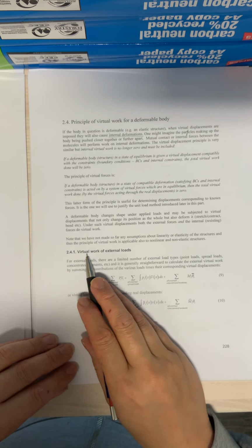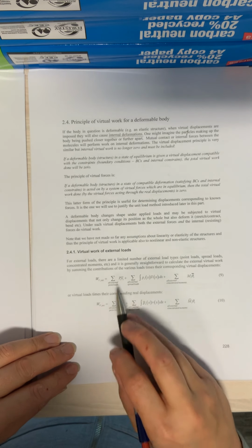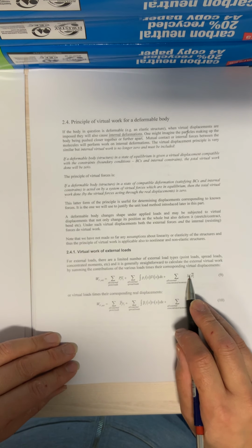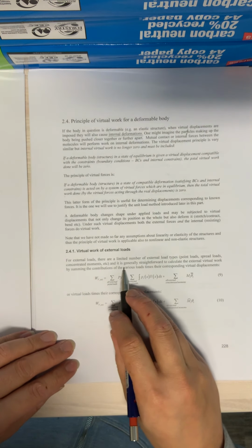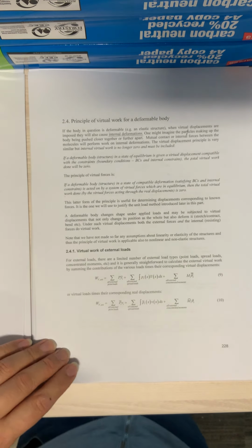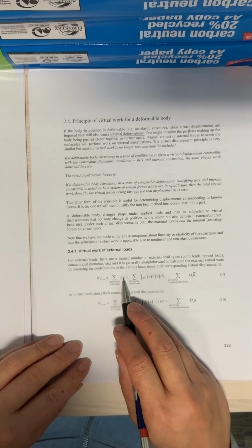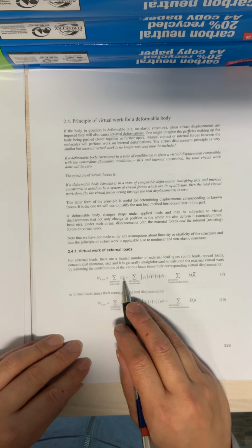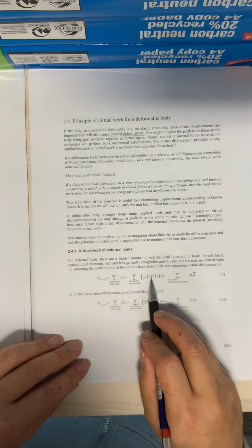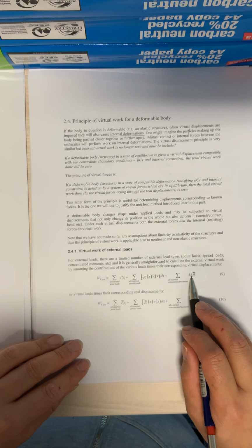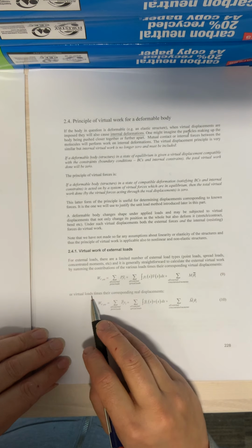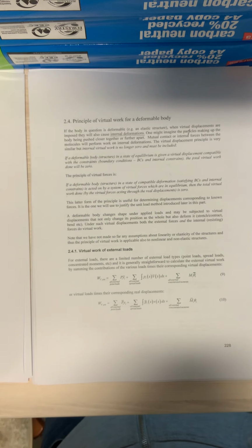So let's work out the external virtual work. We've got point loads P, we've got UDLs, there's moments that you can apply. It's generally straightforward to calculate the external virtual work by summing the separate components together, which is just in the case of P times displacements, the integral here of the UDL multiplied by the displacement of the beam, and the moment multiplied by the rotation, or virtual loads times their corresponding real displacements.